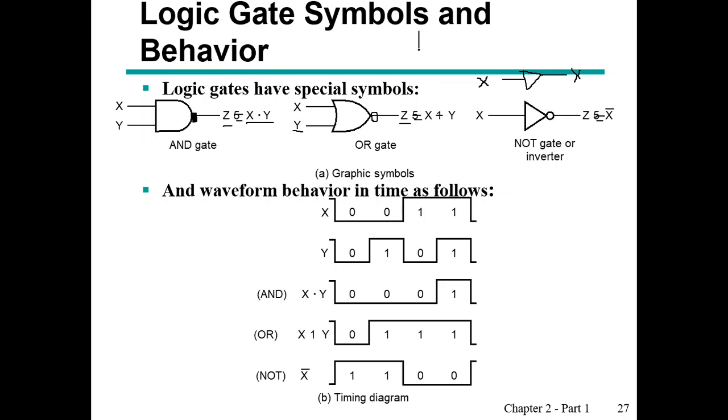So this is your AND gate, and these are its inputs, and you place a NOT gate in series. So this becomes a NAND gate. We don't represent it like this, we just represent it like this. So this is your standard AND gate, and this whole NOT gate is represented by this single bubble here. So this is your NAND gate, not of AND gate.